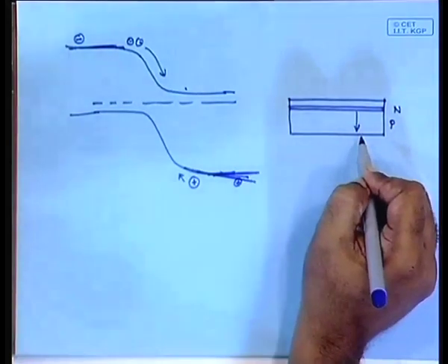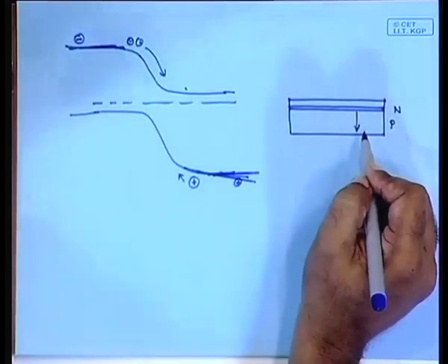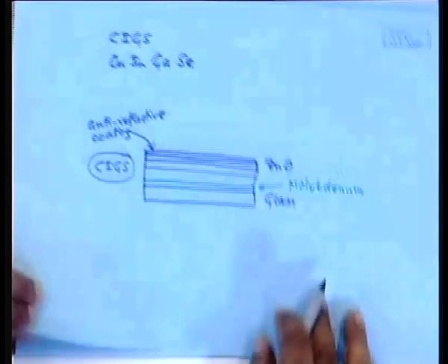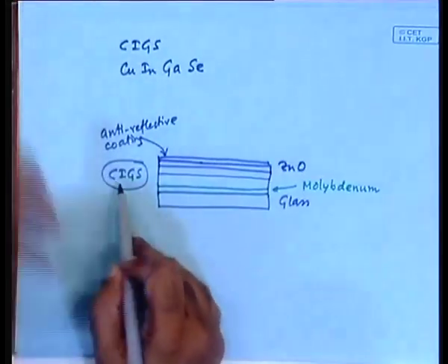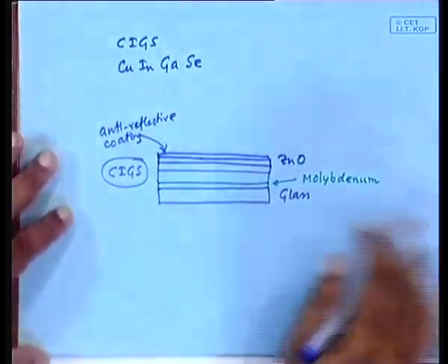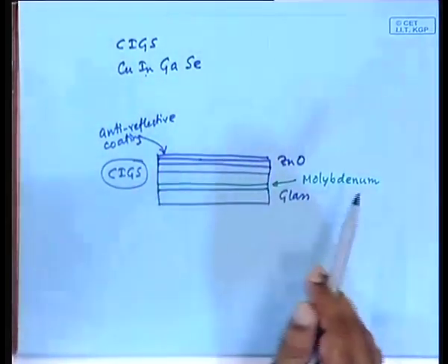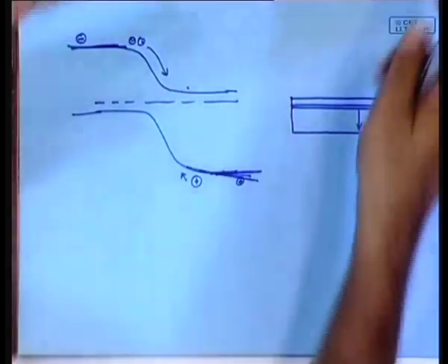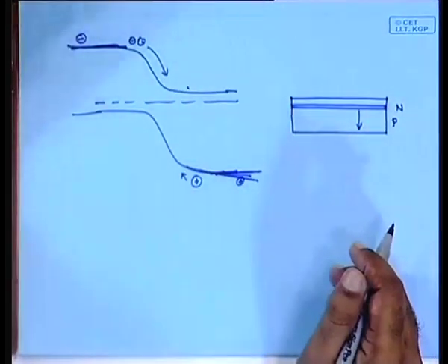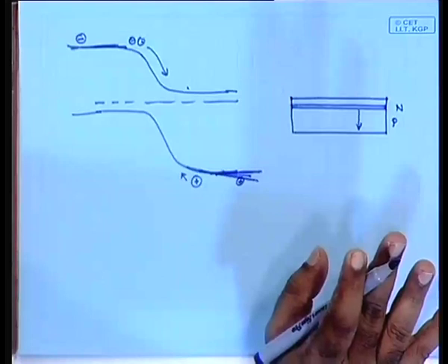So, there are technologies for doing that in silicon as well as in these materials. For example, when I was talking about the CIGS deposition, the concentration of the individual components is varied as it is deposited, and as a result you automatically produce a graded band gap. So, you have this technology inbuilt in all the different types of production technology that we have talked about.